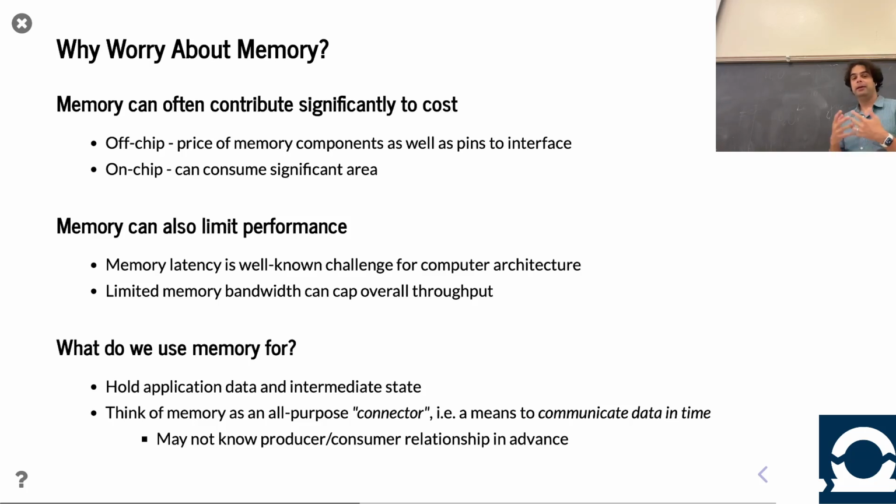If you could get by with using GDDR instead of HBM, that's going to save your team a lot of money, right? On chip, a lot of designs spend at least half of their area on memory, SRAM. Look at a CPU die. Definitely half of your on-chip area is going to be spent on cache, right? Even on a GPU for doing AI, a large fraction of that area is, in effect, memory, whether it be actual caches, scratch pads, or register files. So memory is extremely important. It's one of the most important cost things.